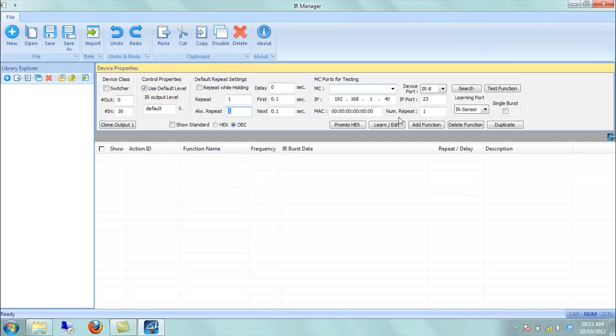Now, here you are able to set up your communication with your master controller, your MC. Your IP address here should, of course, match your IP address of your KD MC2500. Now, we went over these settings in C2 Part 1, working in the MC2500 Device Manager software. But just remember that this third space here should match the third space of your router's IP address, and then the final space is a unique identifier for the KD-MC2500.